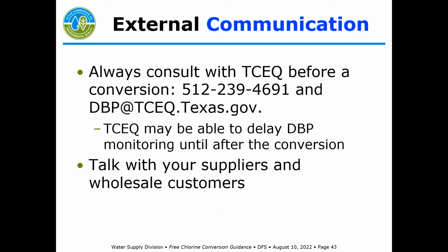You need to talk to TCEQ and let us know that you're doing a free chlorine conversion. The really important reason to do that is you do not want the TCEQ to come out and do their TTHM or HAA5 samples while you're in the middle of a free chlorine conversion, because when you have free chlorine, those things are going to go through the roof. If you discuss it with us, we may be able to reschedule your normal disinfection byproduct samples around that free chlorine conversion, which is a big benefit to you.